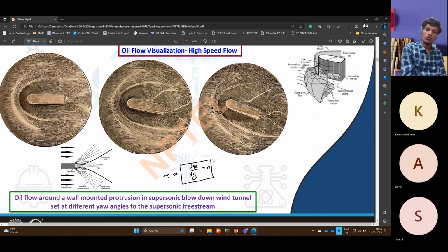Yes. So as your velocity is going to zero, your shear stress, that is the skin friction on the surface, is also going to be zero if it is really this particular portion. If it is really a separation line at this portion, your skin friction is also going to be zero. That is, no effect of fluid at this particular region. Until this point, the fluid flowing above is dragging the oil, because of the resistance. But at this particular discontinuity, what is happening?